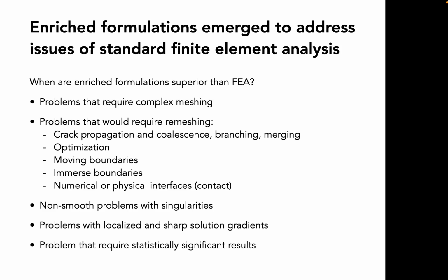We have proposed some new procedures for solving this type of very highly nonlinear problems. And then non-smooth problems with singularities. As I said, you can enrich your solution space with some asymptotic functions that have some sort of singularity towards a crack tip, for instance, to obtain better approximations.